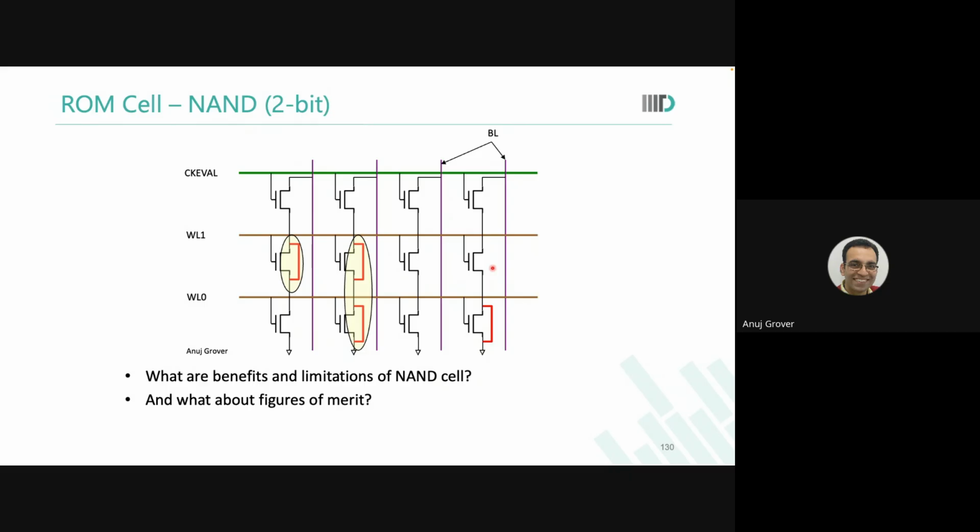In a NOR cell, you have to create those DRC spacings between two cells so that the bitline contact comes on this side, and the ground contact on that side, and whatnot. But in a NAND cell, you don't need to keep all those spacings. So NAND is denser. This will become far more evident when we touch flashes, that NAND architectures are far denser.